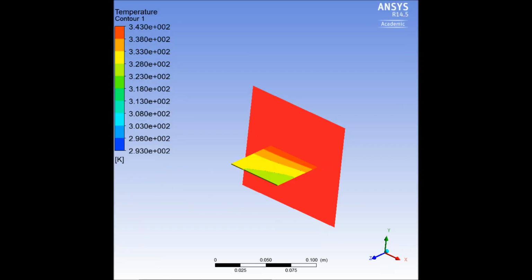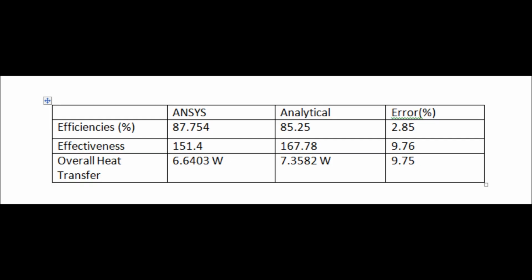In Results or the CFD component, we can also click on Contours in the toolbox to get the temperature distribution for the base and the fin. After conducting such calculations, we should be able to get the exact value for the efficiency and effectiveness of the fin, plus we are able to compare values taken from ANSYS to our analytical results and get the error percentage.